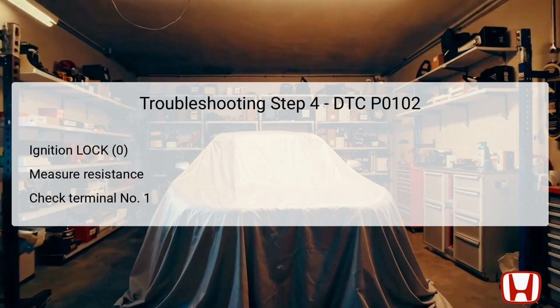After confirming battery voltage, the next step is to turn the ignition switch back to the lock position for safety. Following this, measure the resistance between terminal number 1 of the MAF IAT sensor 5P connector and body ground. This measurement helps determine the integrity of the MAF sensor circuit. A resistance value between 190 to 210 kiloohms is indicative of a properly functioning sensor. If the resistance falls outside this range, this points to possible sensor issues or shorts in the circuit.